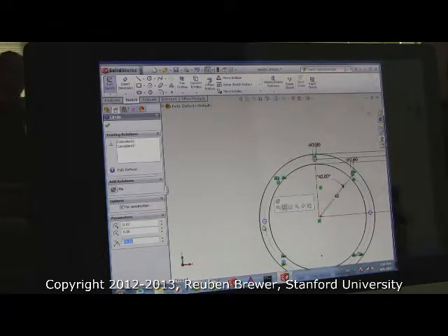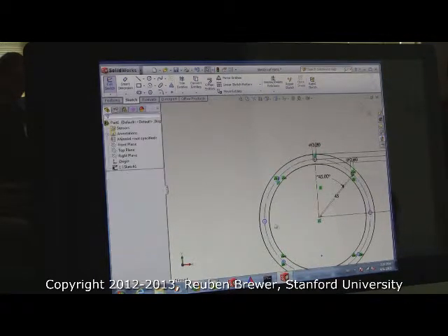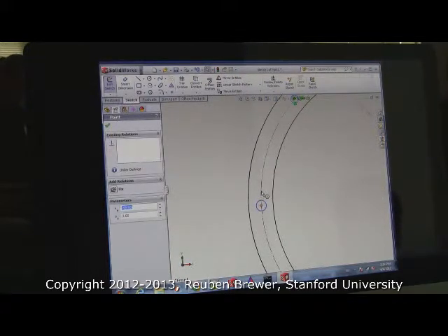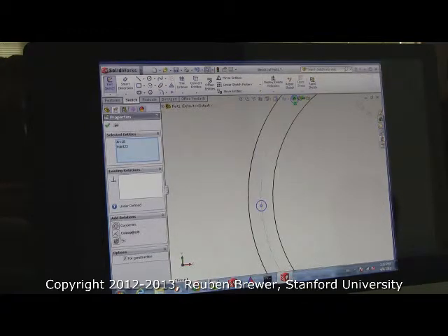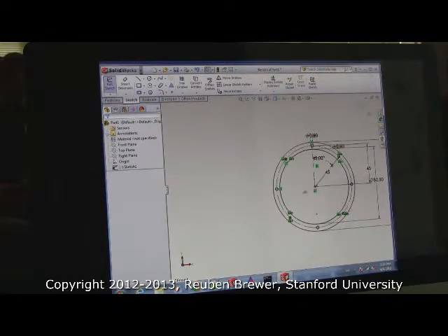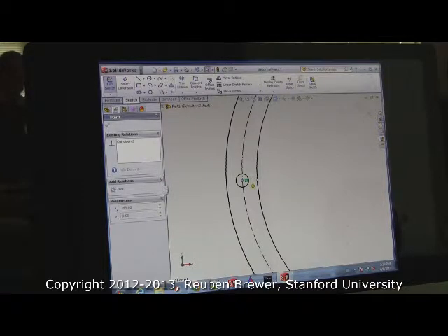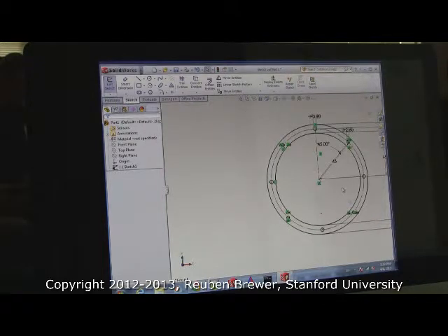Now, it's still blue. That's because for an angular pattern, we need to take two of those patterned things to do it. So now select another blue circle you didn't do. Select the center, control the big dashed circle, and hit coincident. And now you'll note they all turned black. Okay? Now, go back to that circle we dragged before, select it again, and try to drag it. Doesn't drag. It's black, it's constrained. SolidWorks doesn't let us drag around or change constrained stuff. So we're good. Everybody where I am? Okay.